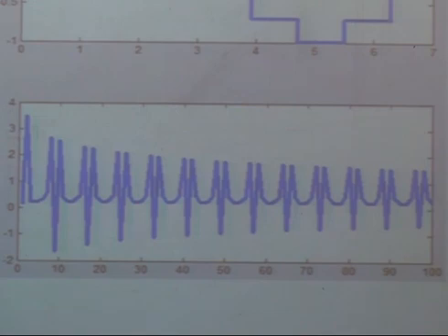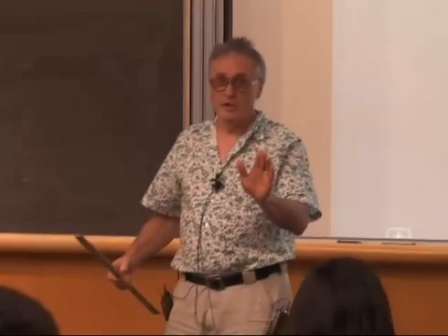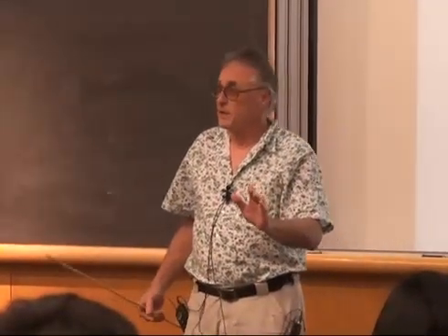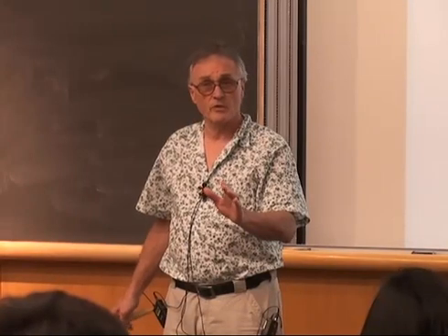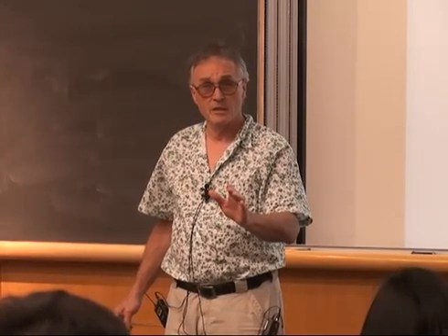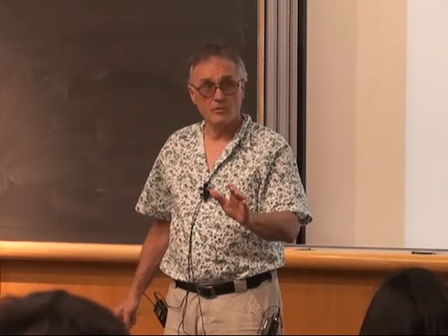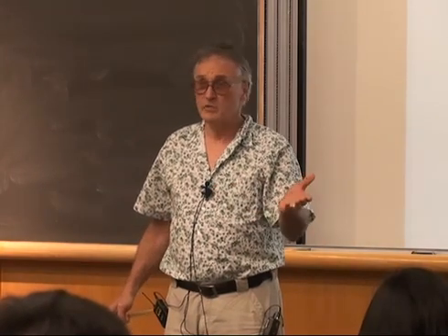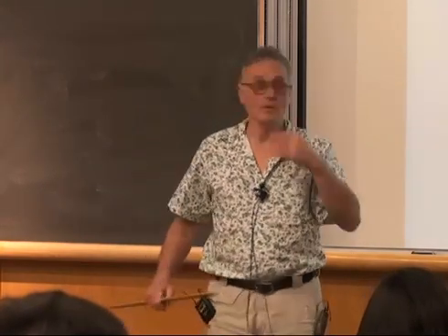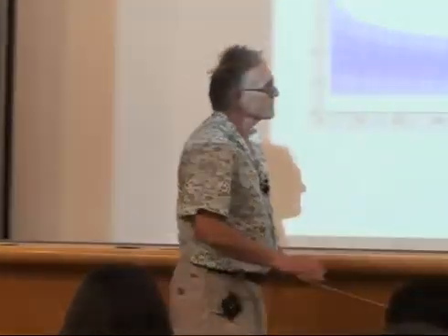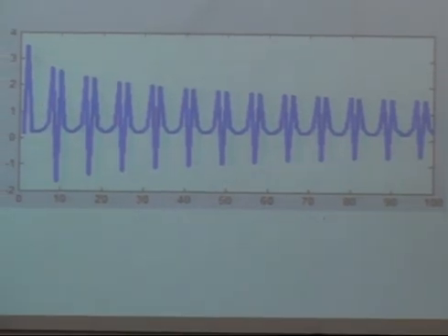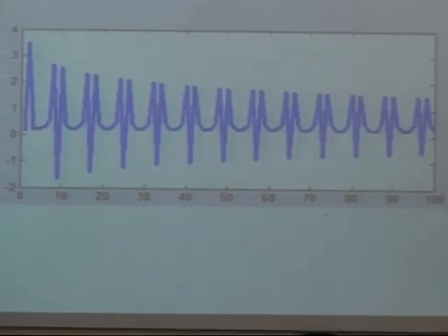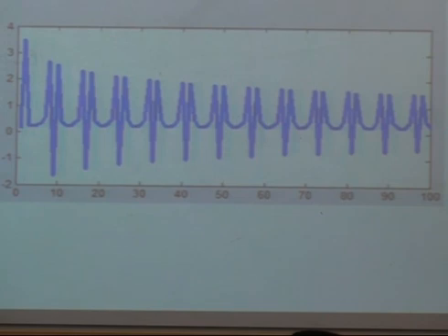You'll hear it. It's almost good enough, though, for the DTMF standard, which I believe is 20 dBs. A factor of 10 is 20 dBs. Now, when you sum all of these error terms up, you'll probably actually get above minus 10 dBs, and so it won't be quite good enough.